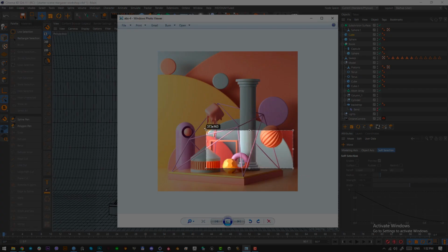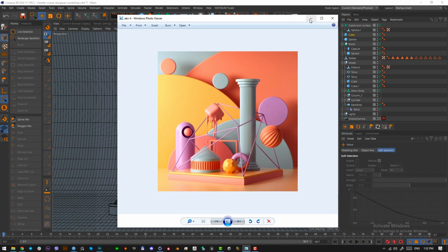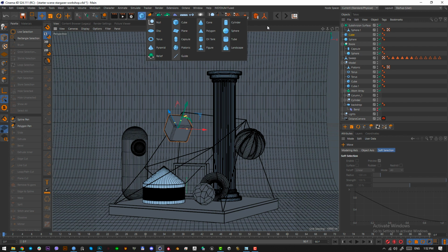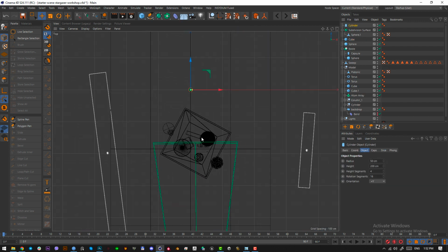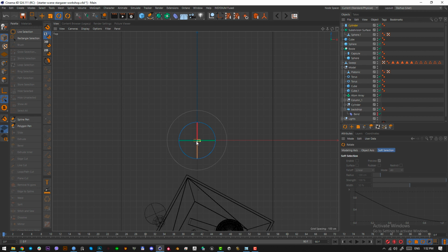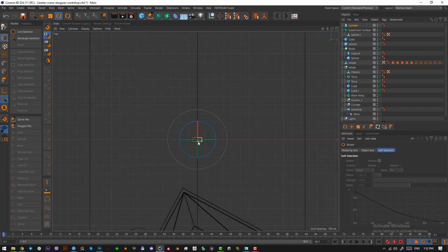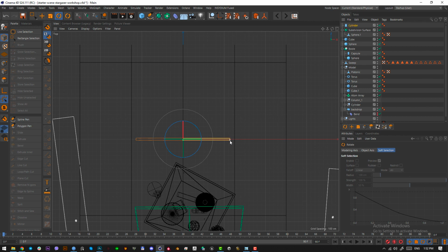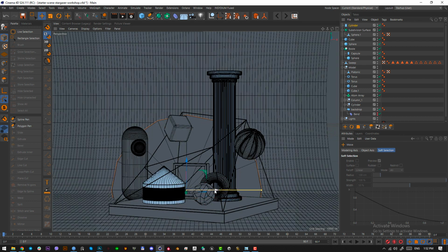So for the background, we have a semi-cylinder here, actually 3 of them, which is making these nice waves. So add a cylinder, press F2, rotate it 80 degrees like this, zoom, change its height, and change the width like this, and put the cylinder here.